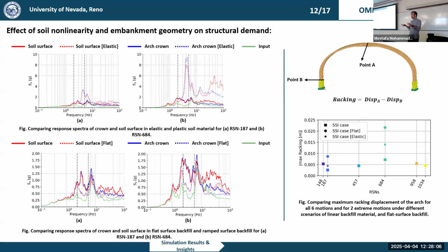although we did not fail in soil, using those nonlinear soil materials made our soil model more realistic. If I just had my soil material model as elastic, I would have some significant jumps and some significant amplification that was not necessary, and it does not happen in the real world, because the real soil is not elastic.